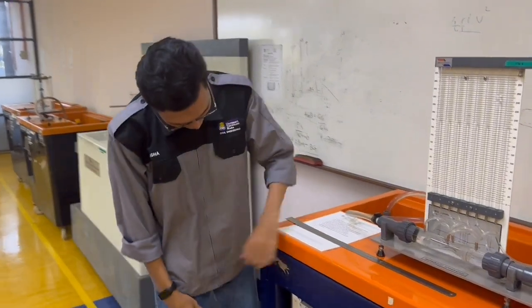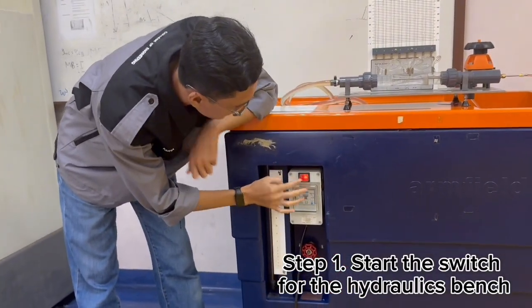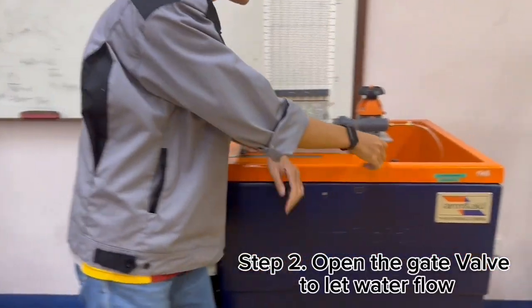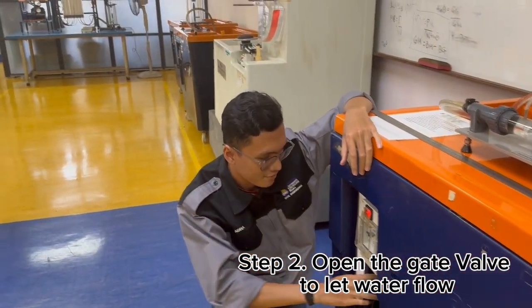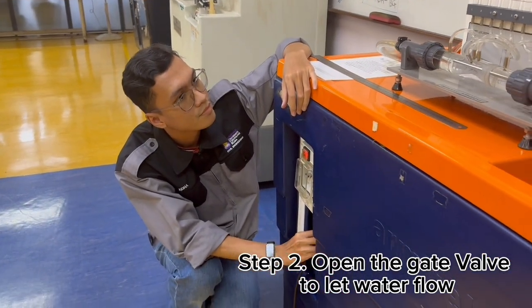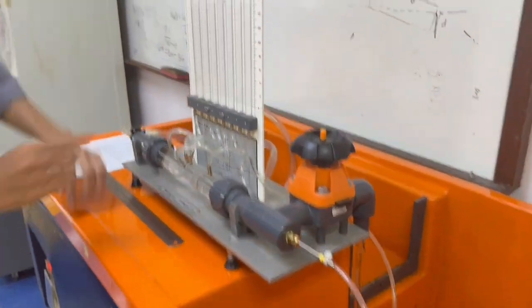So now that we know all the apparatus, we can start the hydraulic bench by pushing the start button, and then we can open the gate valve to let the water flow through the apparatus. This is when the gate is open and water will start to flow through the Bernoulli apparatus.